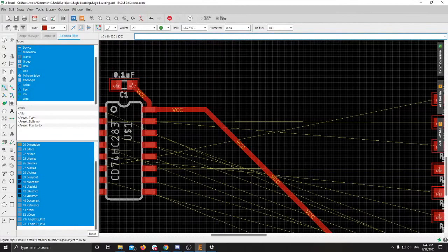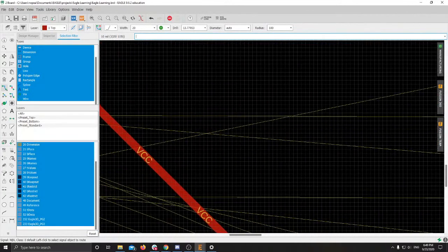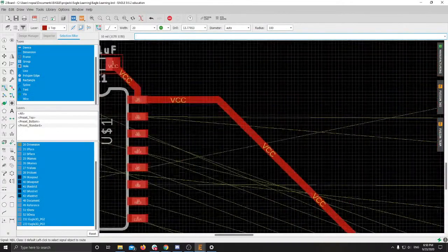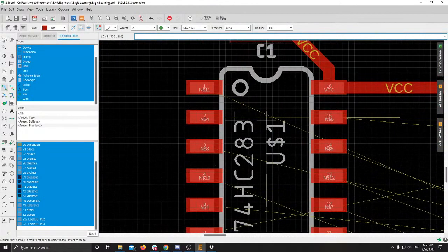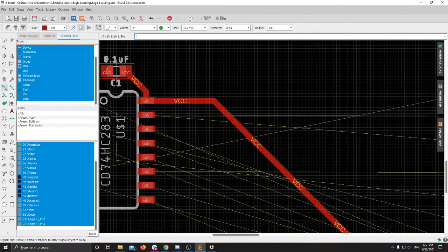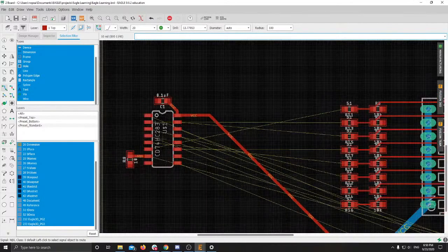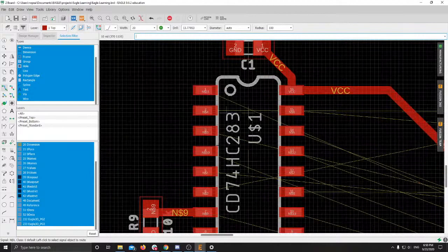All right, so now comes the question. Let's see, I have net 6 here that needs to connect to, did I misfollow that? Oh, yes, I did. So I have net 4 here, we'll start with, that needs to get over to here. How am I going to do that with this trace in the way? The short answer is we are going to weave traces through multiple sides of the board. And how you do that is with what's called a via.